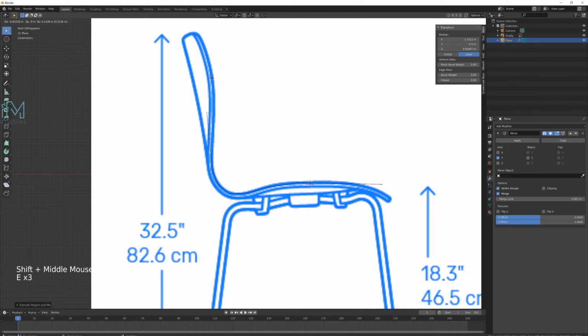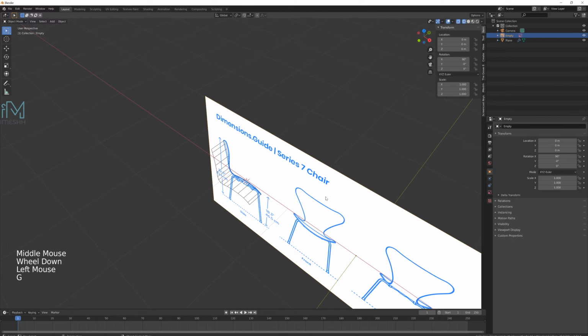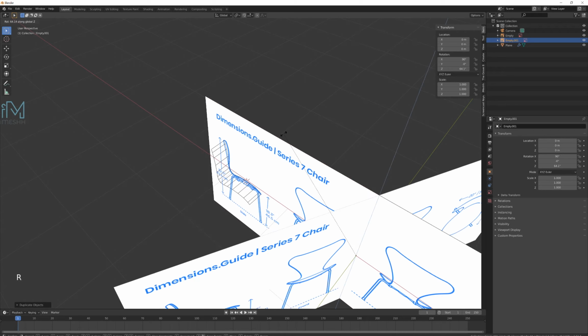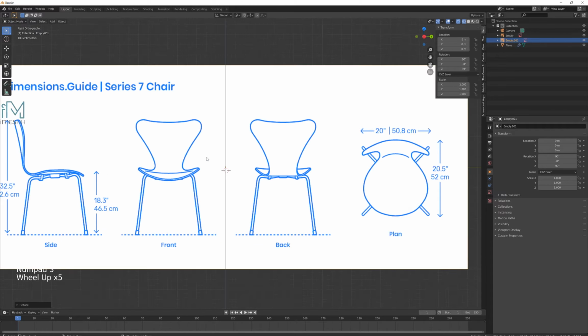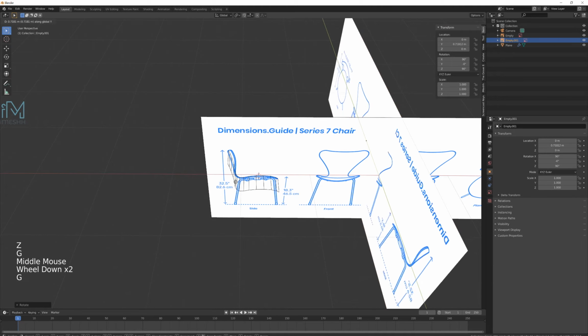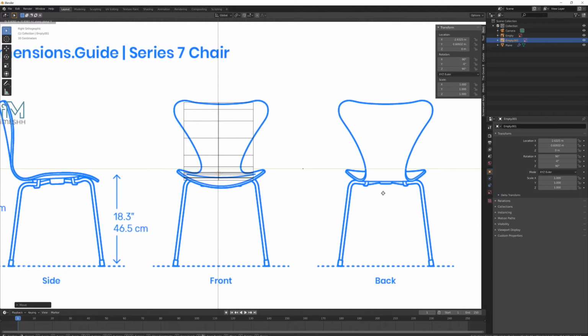I'm actually just going to go straight up here because this is probably where the center of the chair is going to be, and then we'll pull this edging bit out a bit later. And this one is going to go here. Okay, perfect. Now what I want to do is I'm actually going to click on this and press Shift D, and I'm just going to click and type R Z, and I'm going to rotate it 90 degrees. Then I'm going to press 3, and now I'm just going to bring this over here, and I'm just going to align this over here like so.